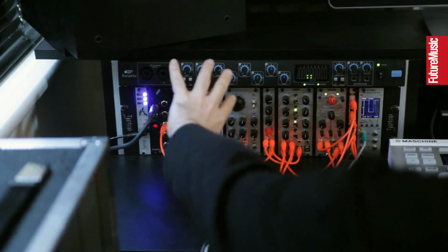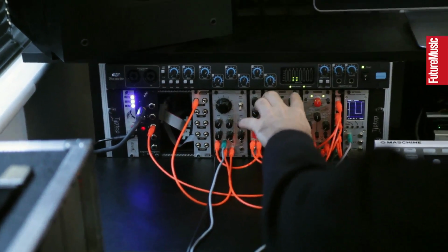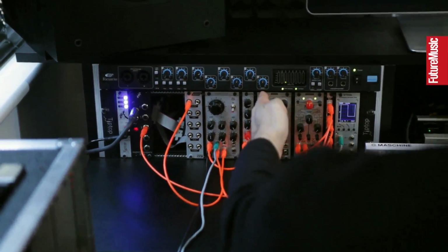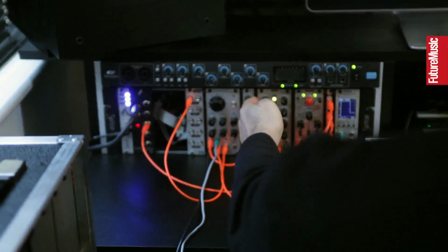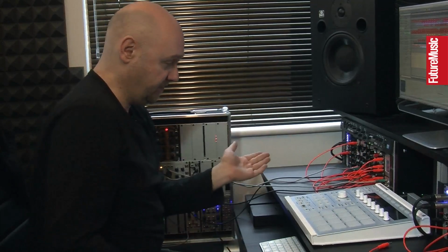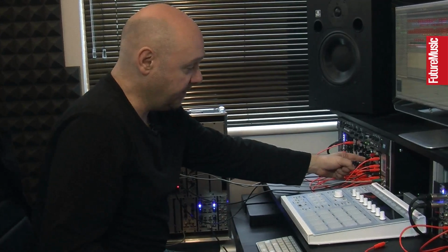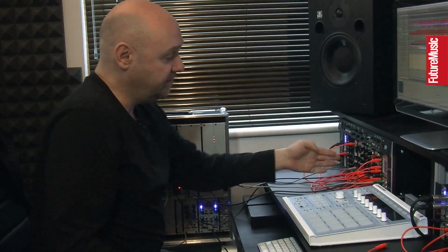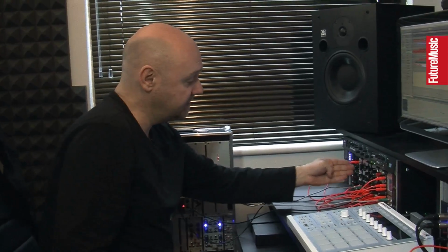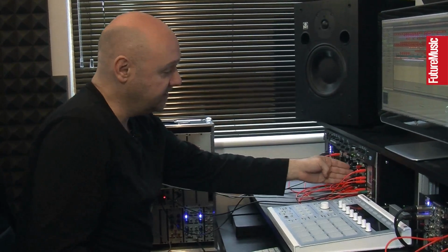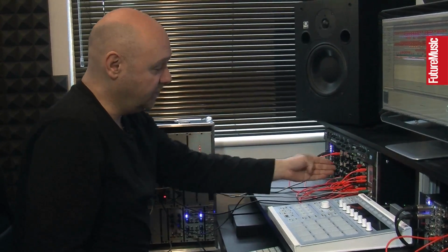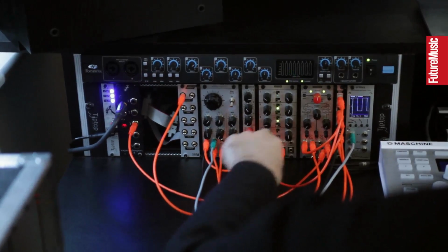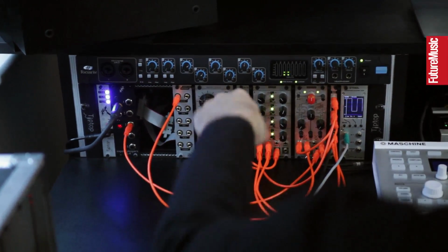This whole synth voice here is pretty much controlled by this IntelliGel Quadra, which just has 4 transient generators, attack and decay, or rise and fall, whatever you want to choose. You can put those in cycle mode, so they can either be basic AD envelopes to open the filter and your VCA, or you can have them as LFOs. I've got 2 of them in LFO mode. They're modulating that filter as well.